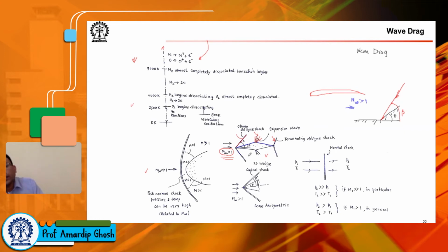So now in case of this wing cross section, you see that M infinity is greater than 1, and something like this is happening, okay? So flow is coming in, flow is coming like that, then it's seeing this deflection and it's bending like that, and so flow deflection is same as this angle, and then we have a shock wave due to that flow deflection. So here you can see that your flow is coming like this, getting deflected by theta. That's why you have a shock wave at angle beta. Here again you see you are coming like this, then you are getting deflected. So you are having that oblique shock here.